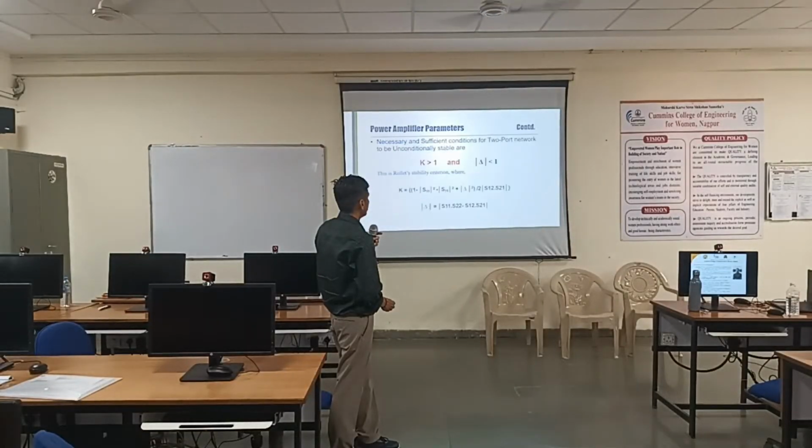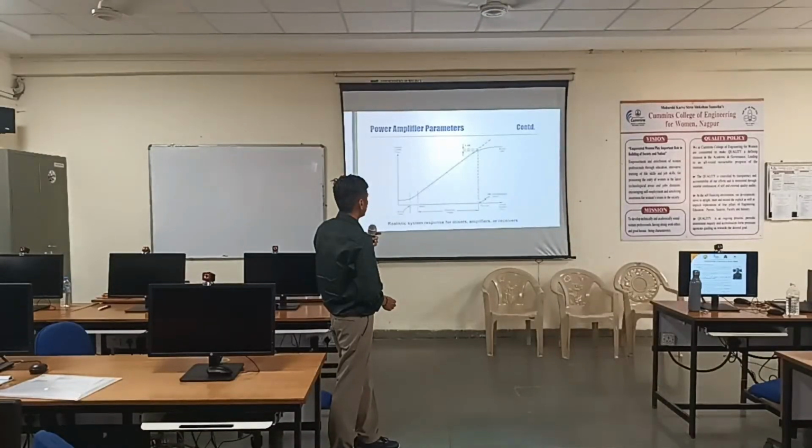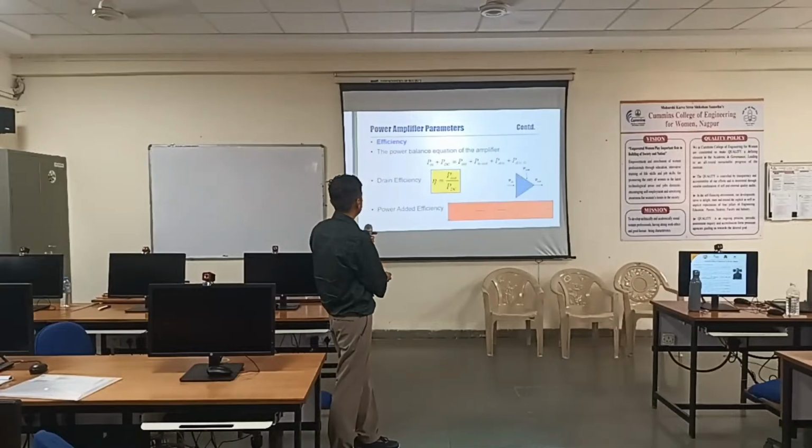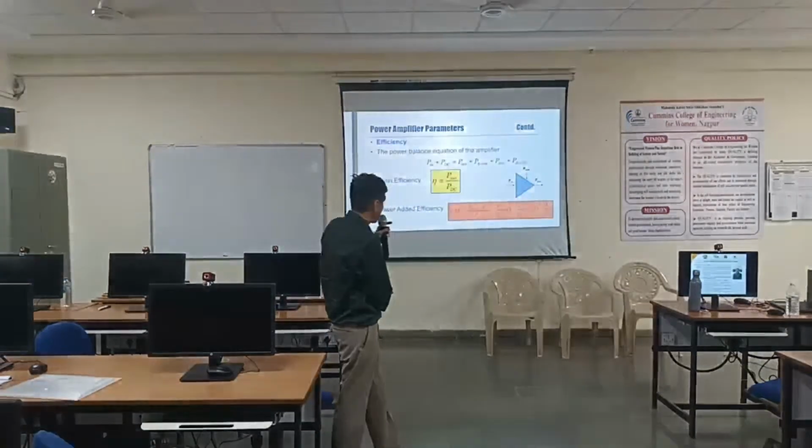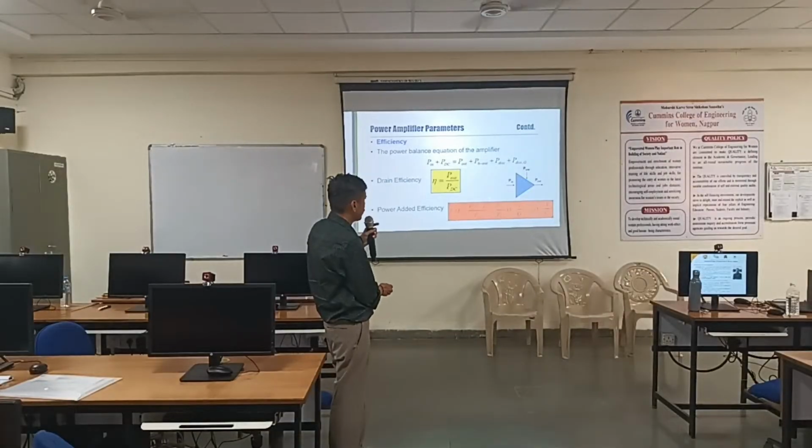No, never possible. So this is the typical efficiency. Output AC upon input DC. We used to call it as drain efficiency, collector efficiency, whatever, depending on the device. Power added: output AC upon input AC.